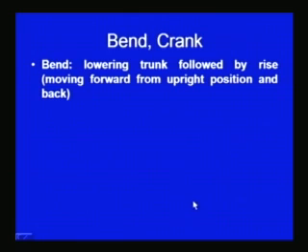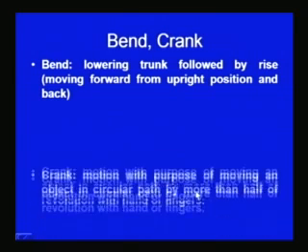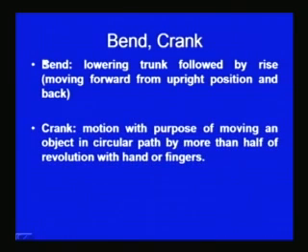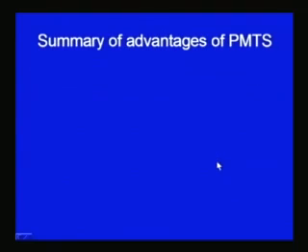Bend and crank are two other elements used in MTM2. Bend involves lowering the trunk followed by rise, moving forward from upright position and back, while crank involves motion with the purpose of moving an object in a circular path by more than half of a revolution with hand or finger.